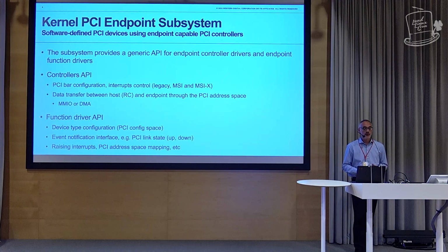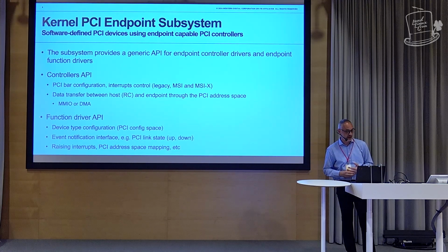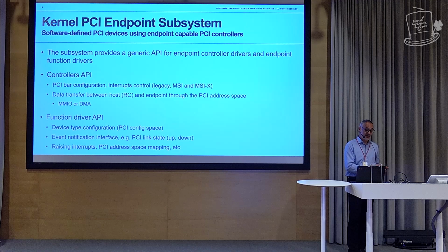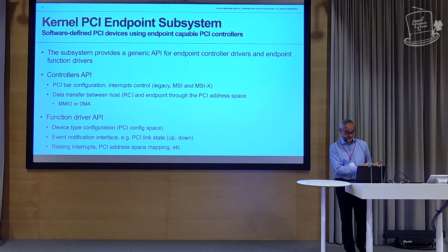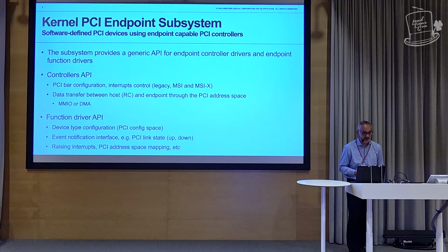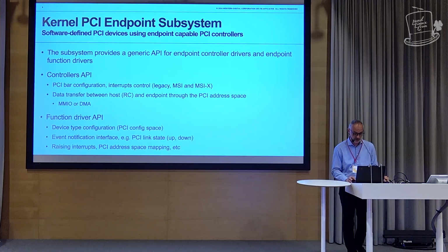and deals with the actual function that will be exposed through the PCI configuration space to the host. So that covers device type configuration, and event notification to the driver about the state of the link with the host. There is also an API for raising interrupts and for doing PCI address mapping so that you can transfer data between the host and your driver. So this is all upstream.